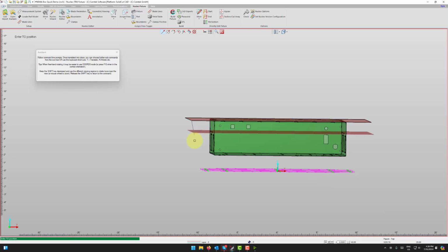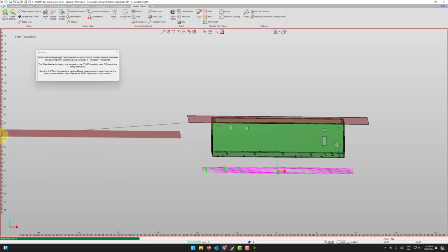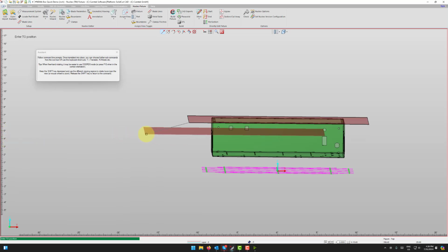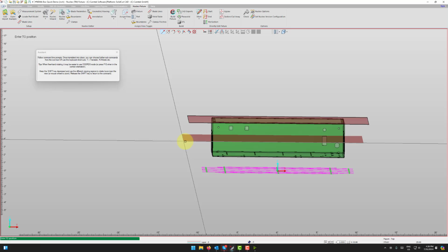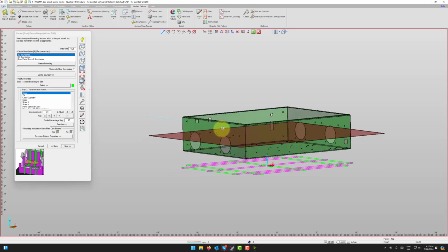So again, freeform, select the boundary, and we're just going to select the endpoint down here. Press T for translate. If we want to be really specific, like maybe we know exactly the height we would like, you can usually look on the left-hand side of Nucleo and you'll have a ruler that indicates heights. You can also just say, I want to be at Z4. So I'm going to tell this point that I have selected, don't move in X, don't move in Y, stay exactly where you are. I just want you to go to exactly Z4, so 4 inches up in Z. We'll press enter, and it's going to show me a preview of what that looks like. Press the check mark to commit those changes. And there we go. It's exactly 4 inches up in Z.